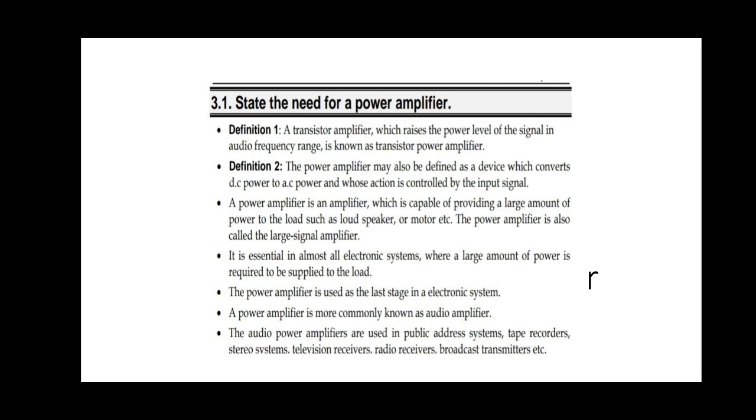That is covered. The effect of negative feedback on gain, bandwidth, input and output impedances we have to discuss. In this, we know the gain formula for negative feedback: AF equals A by 1 plus A beta. So gain stability is increased and gain is decreased. That is the first point we have already discussed, and we derived these equations.